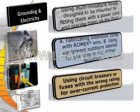Abuses include using multi-receptacle boxes designed to be mounted by fitting them with a power cord and placing them on the ground, fabricating extension cords with Romex wire, using equipment outdoors labeled for use only in dry indoor locations, or using circuit breakers or fuses of the wrong rating for overcurrent protection.